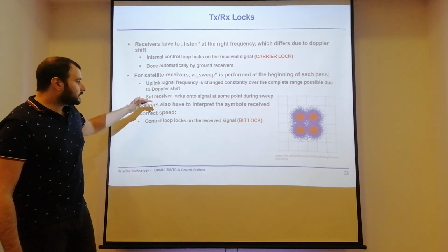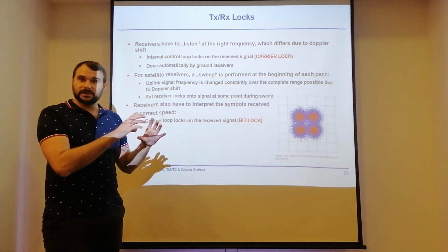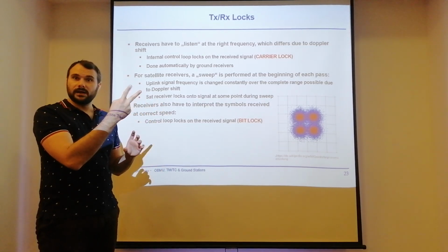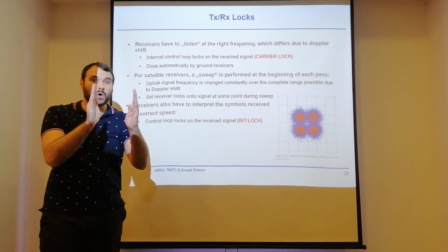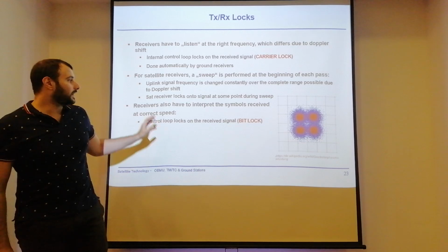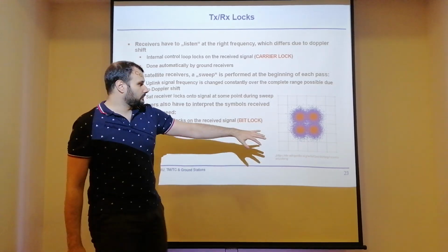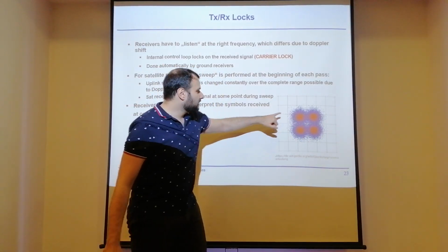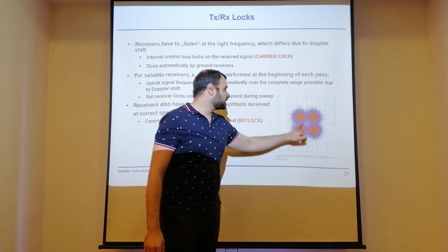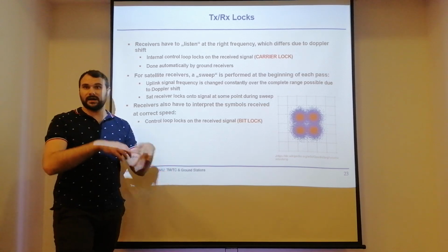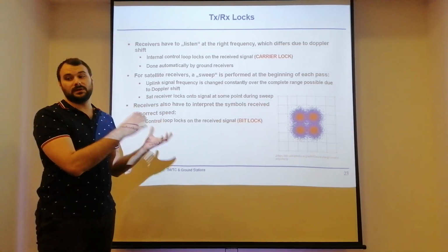And that's why you have a certain sequence where you have a lot of those shifts, and you try to detect the begin and the end of the shift, so you know how long is the duration for each bit. And this is the so-called bit lock, which we see here. You have obviously 4 states here, so it's a QPSK. So at this point, we also have acquired a bit lock, and we can now interpret the single bits.